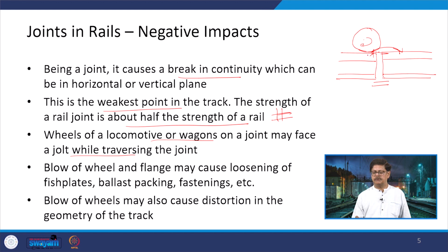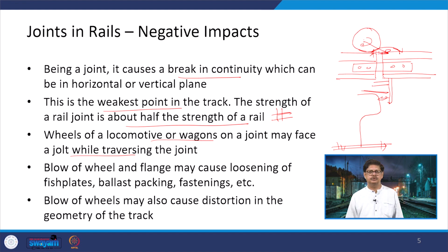because here when you are talking about this and when you convert it into the form of a rail section, and then there is a wheel with a flange. So, if this lateral movement is there, what are the fastenings which are provided at the bottom or being provided at this particular location, say in terms of a fish plate or bolts? Because of this striking and the jolting which is happening here, they may get loosened slowly and slowly.